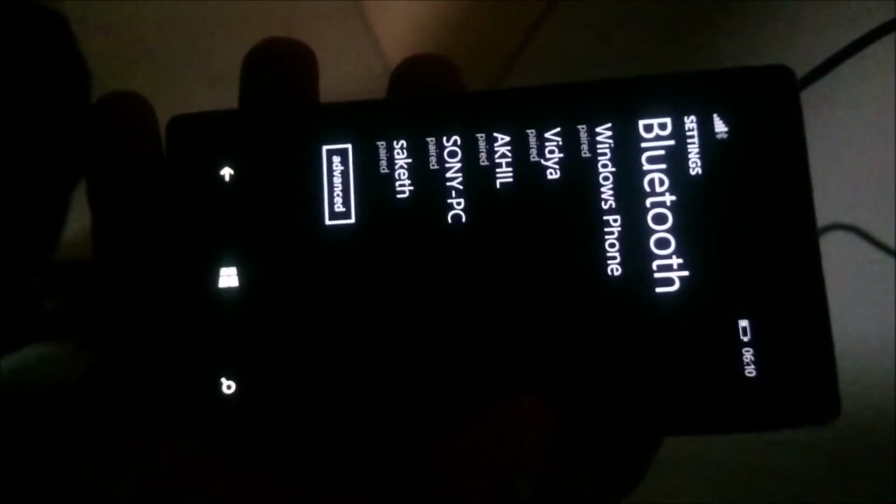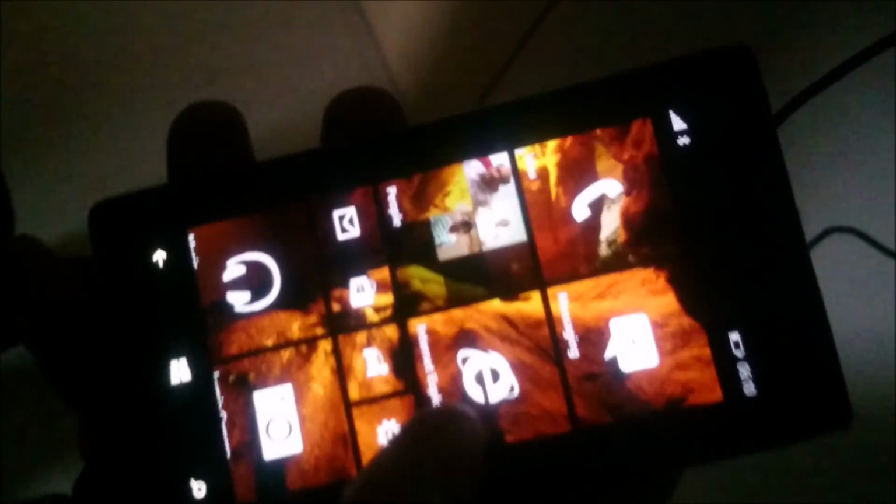Yeah, now if you see here, you have HC05. I'll just tap here and it asks for the pin. So again, 1234 is the default one. So done. Yeah, it's connected. So if you see over the Bluetooth module, again the blinking has changed. It's blinking a bit slower.